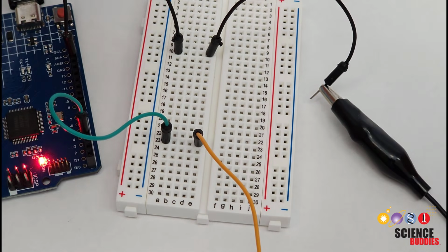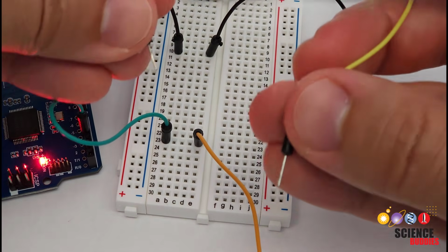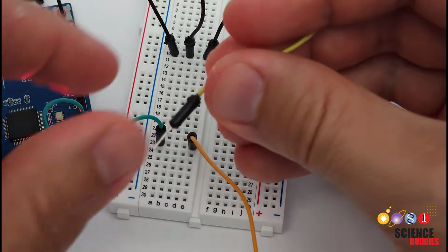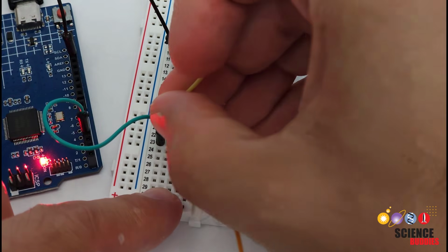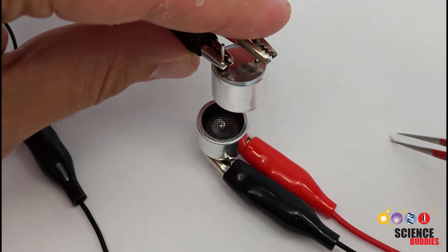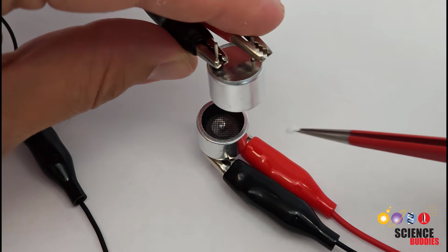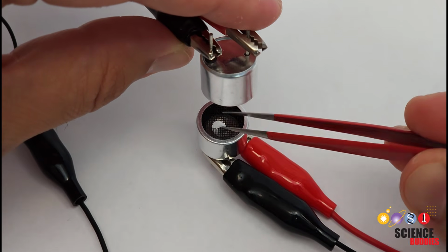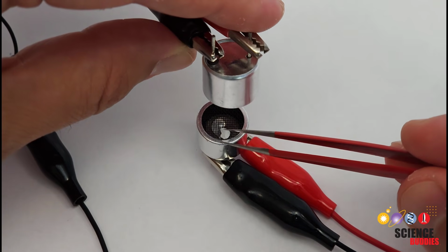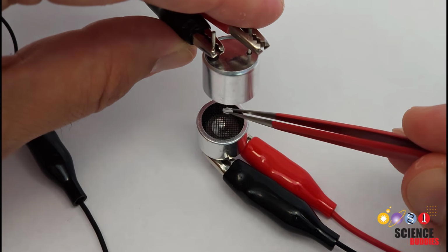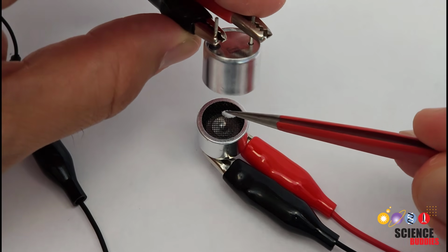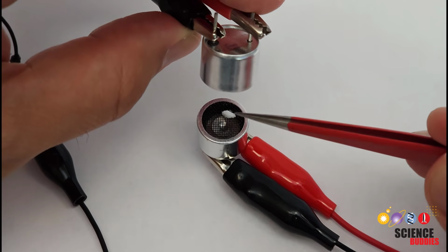I am then going to connect my second transmitter in parallel to the first one, meaning the jumper wires are going to go in the same rows, ground jumper wire there, and the other jumper wire here to the row with pin 3. I can test this by holding one of the transmitters over the other and then grabbing a small piece of packing foam with tweezers and trying to release it in between the transmitters to see if it will levitate. However, we can see that this doesn't really work. And this is because the Arduino pins are not really powerful enough to drive the transmitters directly and generate powerful enough sound to get the levitation effect.